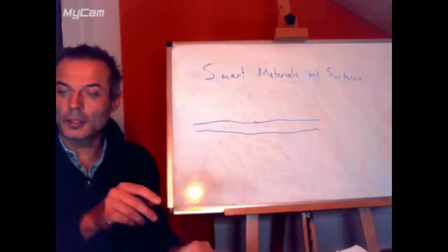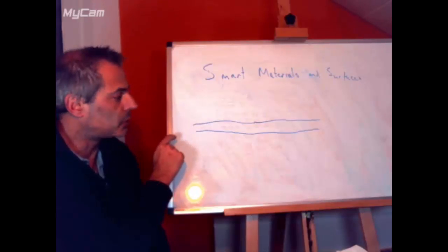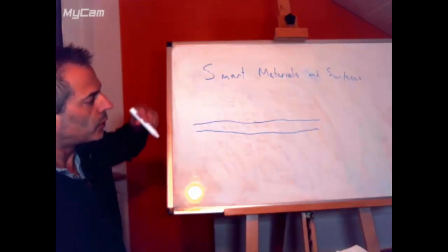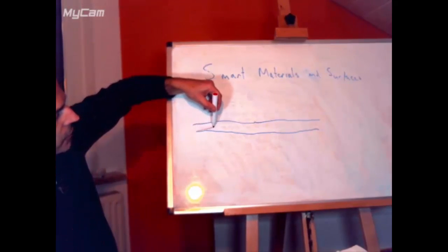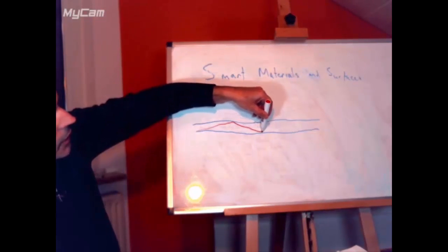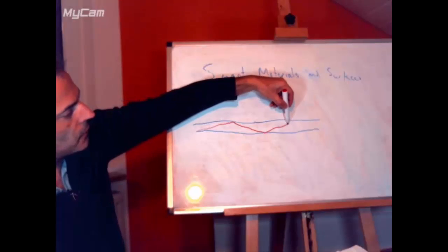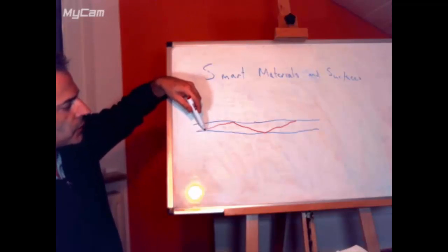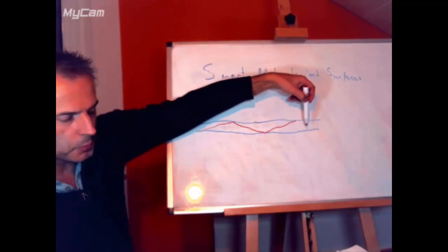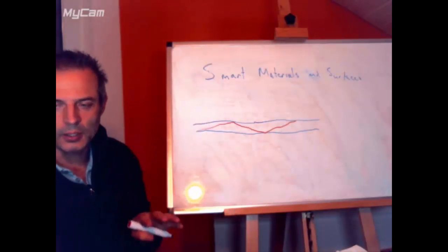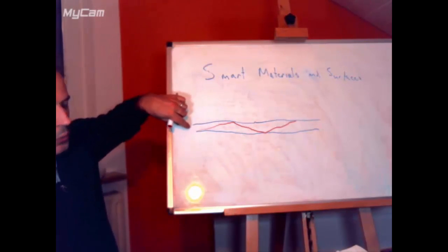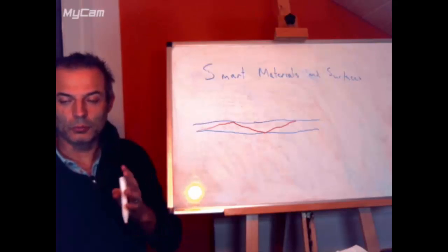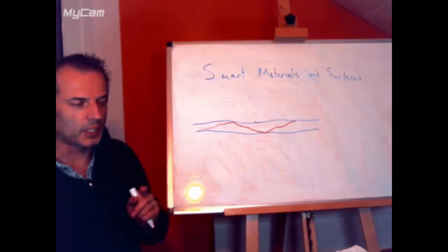The next thing that I would like to think about is if we have an optical fiber, for example, and we pass some light down it. The light doesn't pour down there like it's a tube. It's bouncing off the inside faces at different angles. So we don't couple the light in perfectly parallel. Some of it is bouncing at a steeper angle and some of it is going almost perfectly down the center. And it will depend a lot on how smooth the outside is and whether it's bent into curves, how much the light interacts with the sides, and whether the light that interacts with the sides is always the same light.